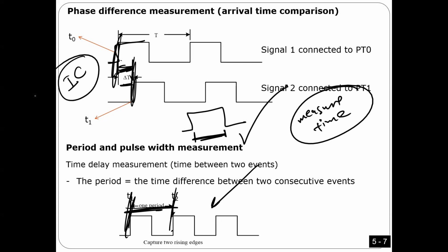I see, input capture. Input capture is made so that it can measure time efficiently. I'm going to give you more details, but just keep in mind, every time you want to measure time, for example, the time difference between two signals, or the time from here to here, the best and most efficient way to do it is using what we call input capture. This is the main functionality of input capture. Don't think about it: if you want to measure time in a signal, input capture, done.